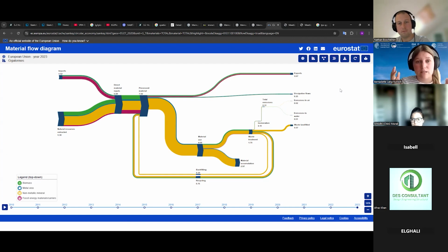For example, oh, it's easy to manufacture, but as soon as we start to disassemble a brick and mortar wall, a lot of the time the bricks break because the mortar is too strong. Maybe in the beginning, we need to find a better solution for the mortar, so that it's easier to break up, or we find a better solution to use the broken bricks. Then we are starting to talk about the solutions, but it's always good to find the, I want to say, scary bits of our material flow analysis to understand where we need a solution. And then it's a fun task to find a solution for.